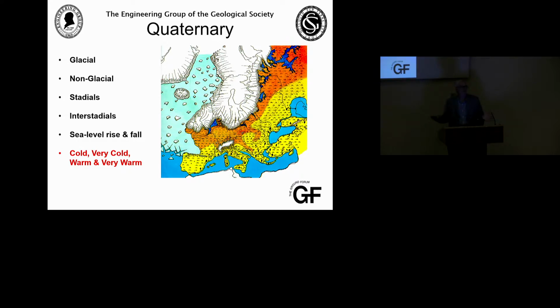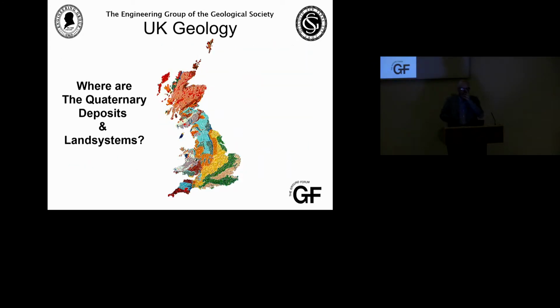Now you say, that's just climatic fluctuation, but in geotechnics, that becomes significant because these are the materials we're encountering. They've had this post-deposition modification and weathering. We've got the climatic fluctuations to really understand what's happening to the fabric, what's happening to the strength of those materials.